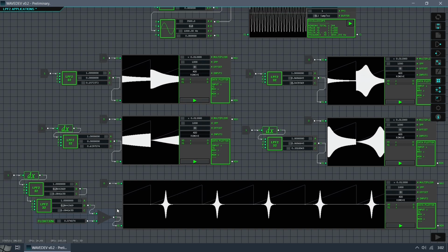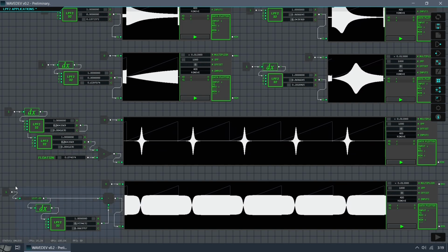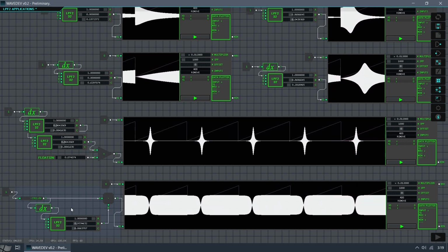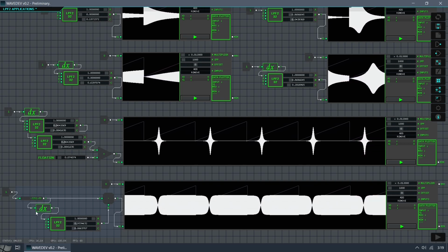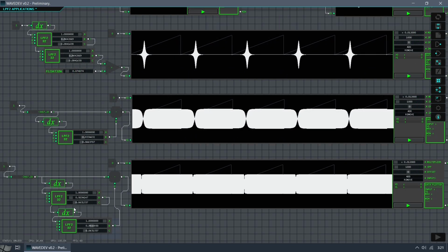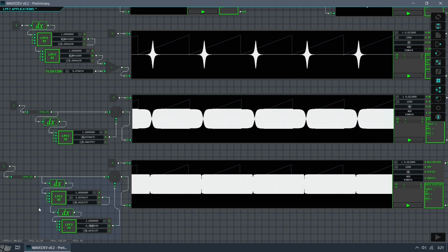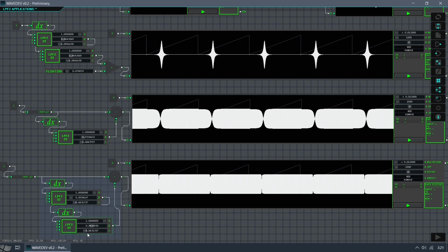To suppress specific frequencies without altering the entire spectrum, there is also a notch filter configuration. This notch filter can be more selective if we duplicate the resonant filters. Although this is more complex to adjust since we need to find the right parameter combination.